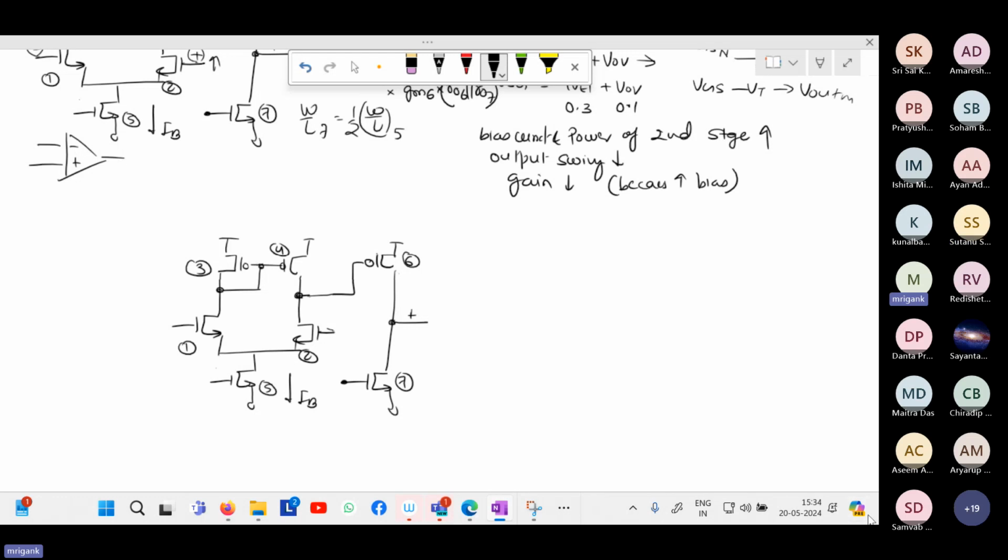Yes. So in this amplifier, for the high frequency pole, this node is a low impedance node. Let me call the nodes A, B, C, D. For differential operation, node D is not consequential. We assume it is AC ground, right? So node D is not important. Only for common mode gain will it be important.